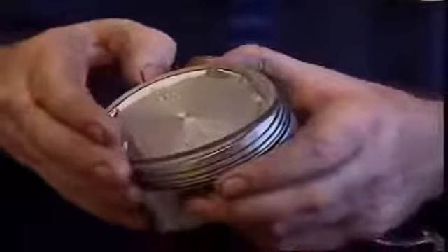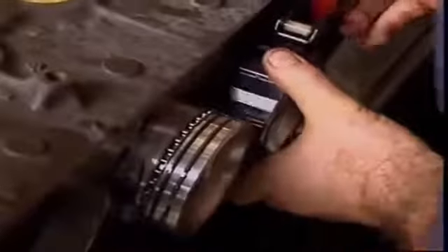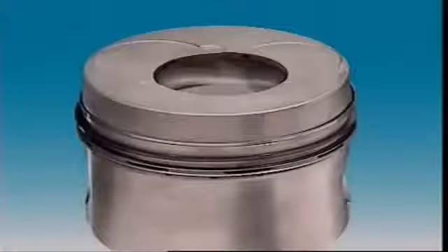They are split so they can be fitted into grooves in the piston and to expand against the cylinder walls. When they're removed, their diameter's larger than the pistons, so when they're installed, they're compressed and the gap is almost closed. Tension in the rings keeps them against the walls.